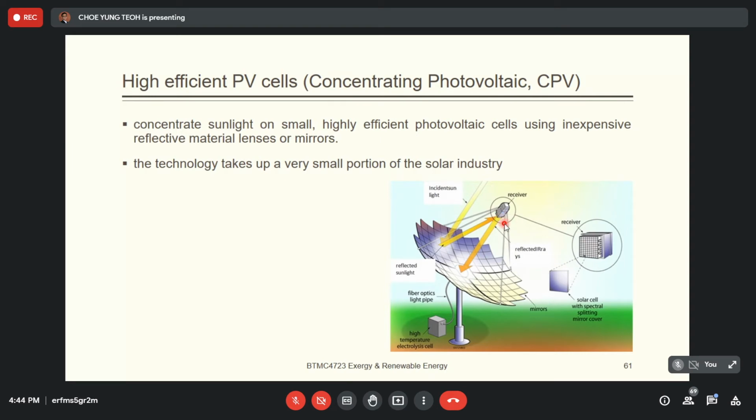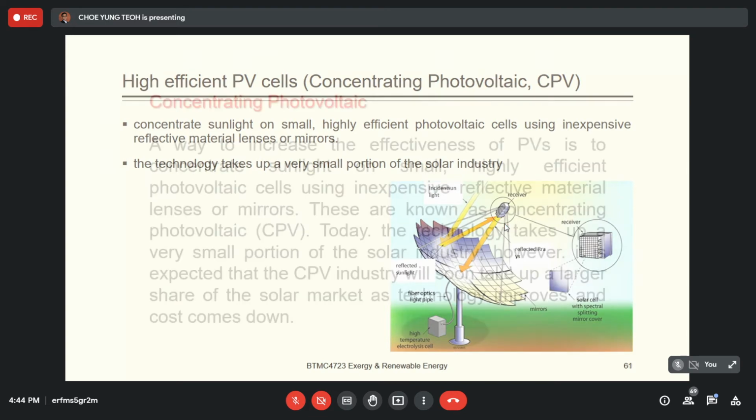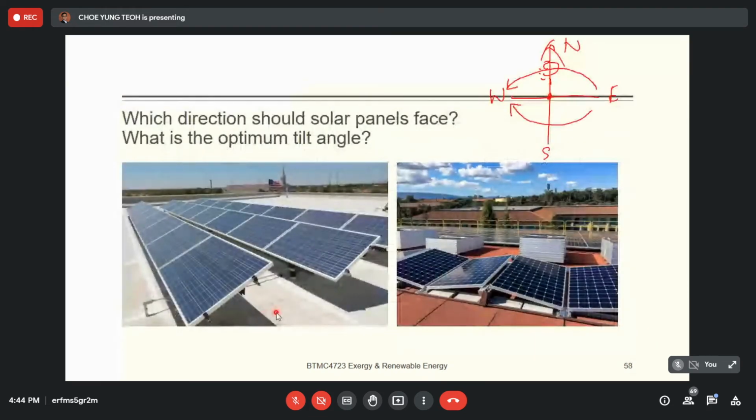So in this case, you need to do the cooling. For this arrangement, normally we do not supply active cooling. We just give a space at the bottom. Even if I attach it to the rooftop, I will also leave a little space between the panel and the rooftop so that the heat can be dissipated. There can be heat loss by conduction, but we do not have an active cooling system which supplies water or cooling, because it won't be too hot.